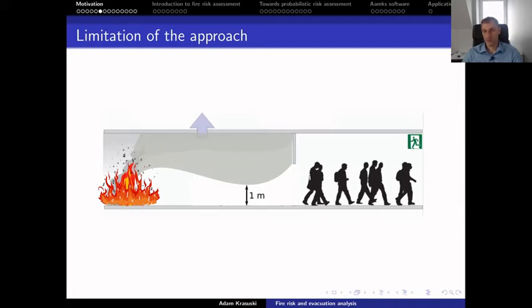One of these is that the critical value of the fire environment can be achieved in a place in the building where there are no people or they have already left. For example, the fire achieved its critical value on the 8th floor and the people are on the ground floor. In the direct understanding of ASET and RSET analysis, the building is not safe because ASET is shorter than RSET.